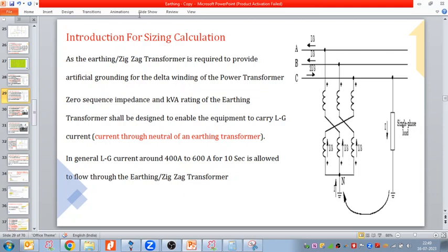In a recent design, I got a drawing with a final distribution transformer with neutral grounding. So it's not possible, no? Recently I got a design drawing, in UP actually, where the final transformer has a neutral NGR. I told them it is not possible. During the fault, the neutral voltage goes up.